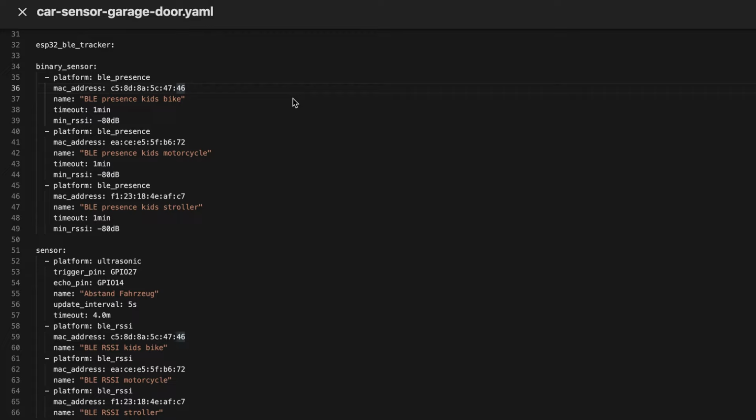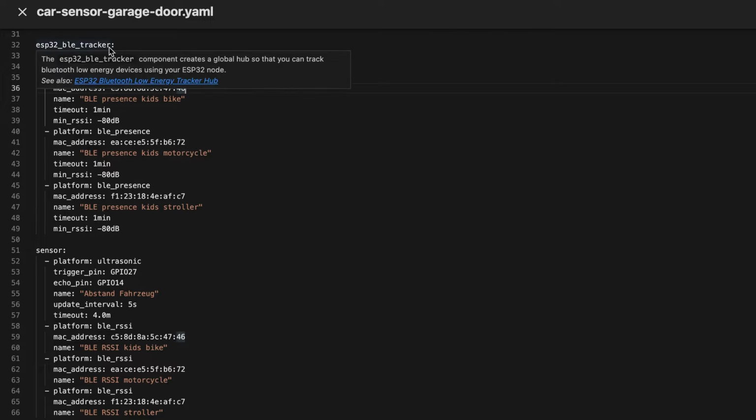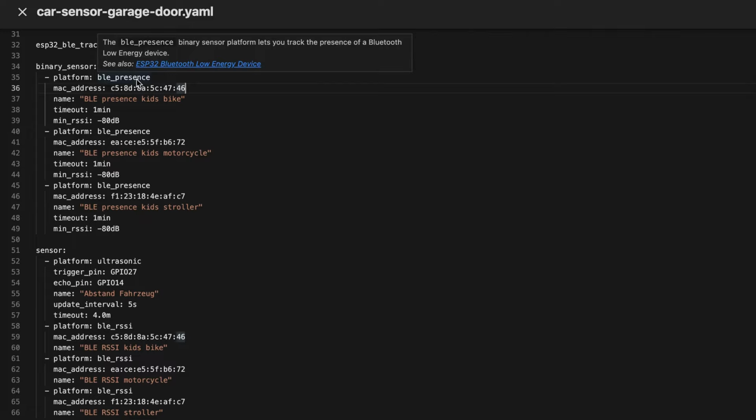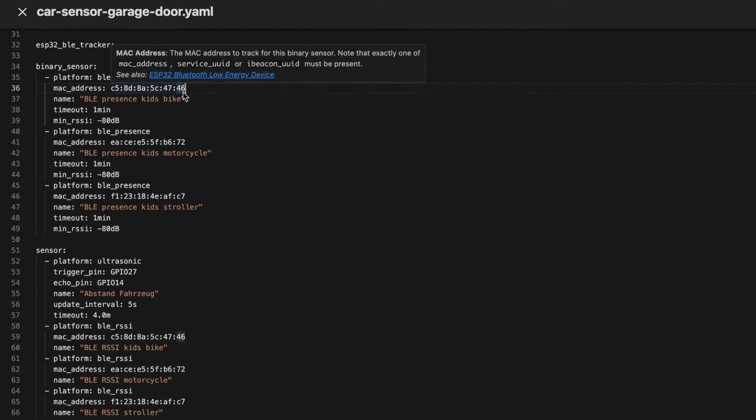But this is not the scope of this video here. In this video I would like to explain how you can just use any existing ESP32 ESPHome node in order to use it for BLE tracking. So you just have to add this line of code, ESP32 BLE tracker, and then we can create some binary sensors of platform ESPresense, which track whether the MAC address, and this is the MAC address of your BLE beacon.